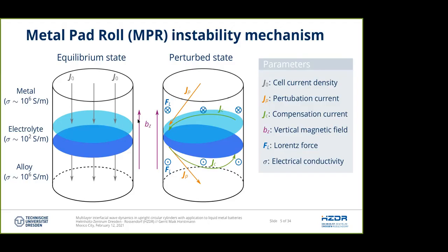Magnetic fields are always unavoidable, both in liquid metal batteries and reduction cells, because they arise due to the feeding lines. They can be pointed in different directions, but in this ideal case we consider only the Z component, the vertical component of the magnetic field, because in this situation the current and B are parallel, so we don't have any electrovortex flows.